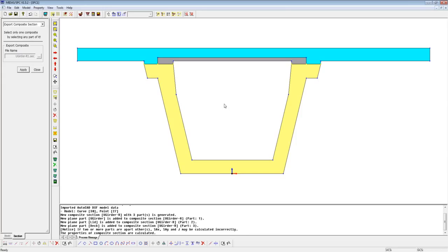And to consider the haunch, if you really want to consider its load, and you want to be accurate in the dead load effects, then you can consider the weight of that haunch onto the structure as well. So in that manner, you can consider the variable cross-sectional properties due to the different haunch heights. There is hard to find a platform or a spreadsheet that will consider all those variations.